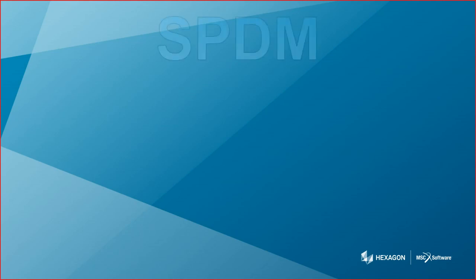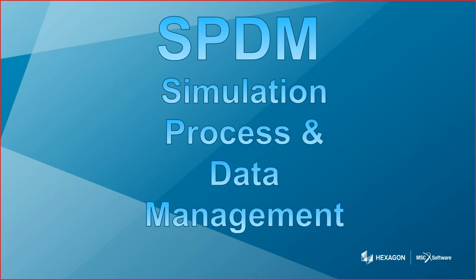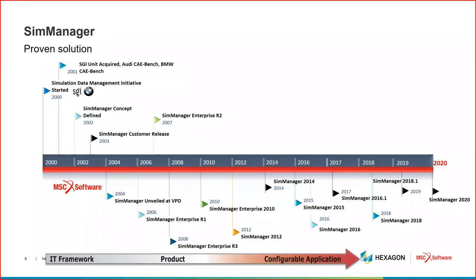Really, SimManager sits within an environment generally known as SPDM, where SPDM is simulation process and data management. And as I say, today is very much focused on the data aspects. So think of SPDM as the simulation equivalent to PDM or PLM. We're not dealing with design models here, but with the analysis models, be they structural, thermal, CFD, acoustics, whatever is required in the analysis domain that complements the design structures typically existing in PDM.